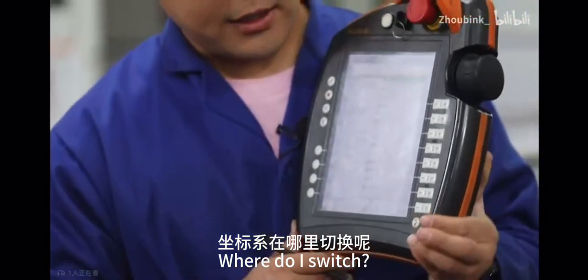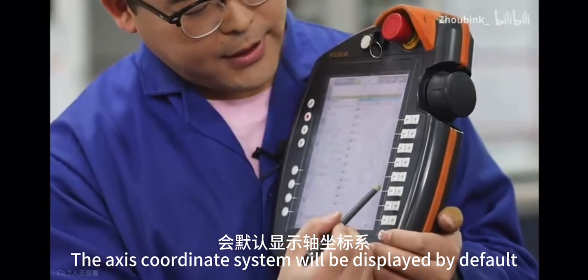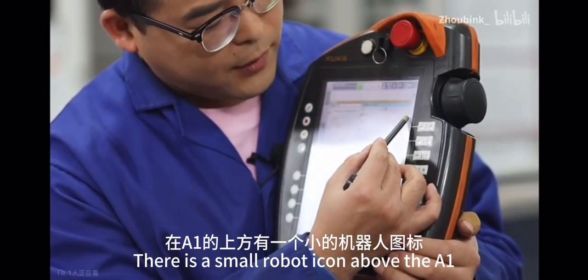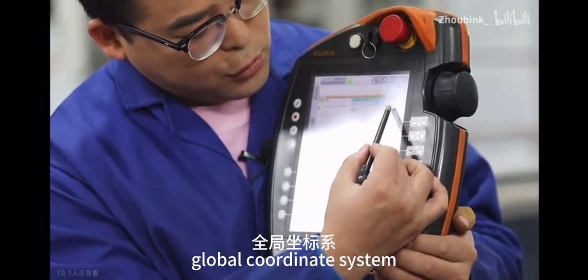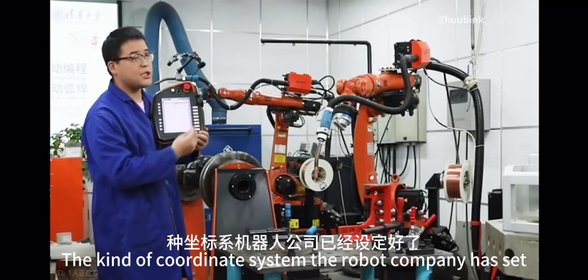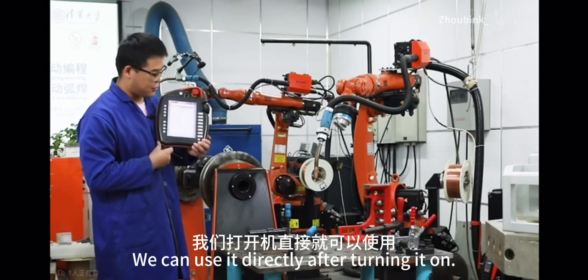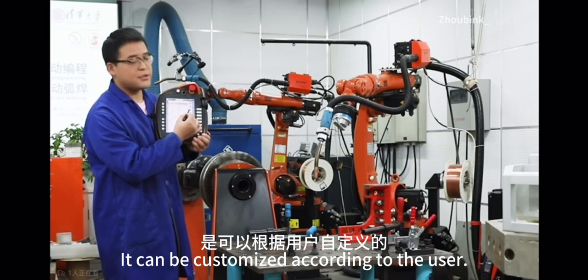Where do I switch? What about after we turn it on? The axis coordinate system will be displayed by default. There is a small robot icon above the AE. Click on it and it will show an axial coordinate system, global coordinate system, machine coordinate system, and tool coordinate system. The kind of coordinate system the robot company has, use it directly after turning it on. The latter 2 coordinate systems can be customized according to the user.